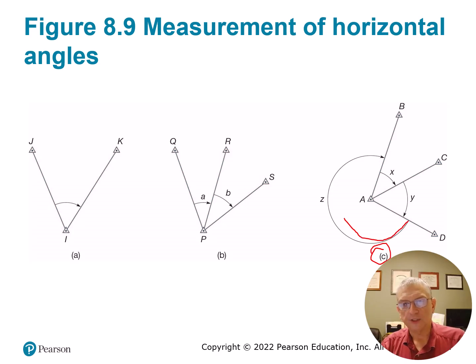They call it closing the circle or closing the horizon, where when you've got some angles added up to get a check, you would add up, you would turn the outside. So let's just say that X is 40 degrees and Y is 50 degrees. That's 90. So Z should be 270. Now, obviously, you dial that down to the second that was actually observed.